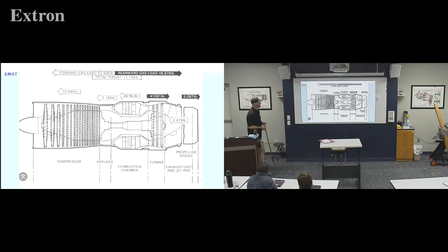So the front of the engine's trying to leave us. The next section, which is our diffuser getting ready to send it into our combustion chamber, is also trying to leave the engine. And you go, there's no blades in there. Why is that one trying to leave the engine? Well, we went from a high pressure to a lower pressure in our combustion chamber, right? Because in our combustion chamber it expanded, the volume went down. So same idea: that section where we went from the highest pressure into a lower pressure, that pressure alone is trying to leave our engine out the front too.